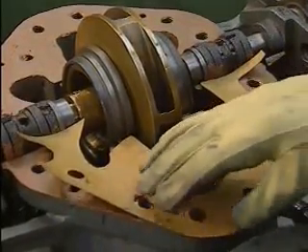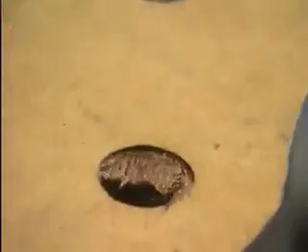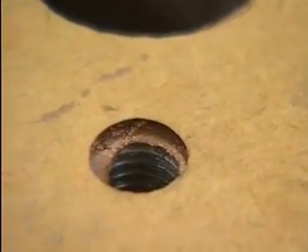He carefully lines up the gaskets with the edge of the pump casing and checks to make sure that all the bolt holes in the gaskets are properly aligned with the bolt holes in the casing. If the bolt holes don't line up perfectly, the holes can be punched again to slightly enlarge them. Forcing bolts through holes that are incorrectly positioned could cause the gasket material to tear, and the gasket might fail as a result. If the gasket is torn during installation, it should be replaced.